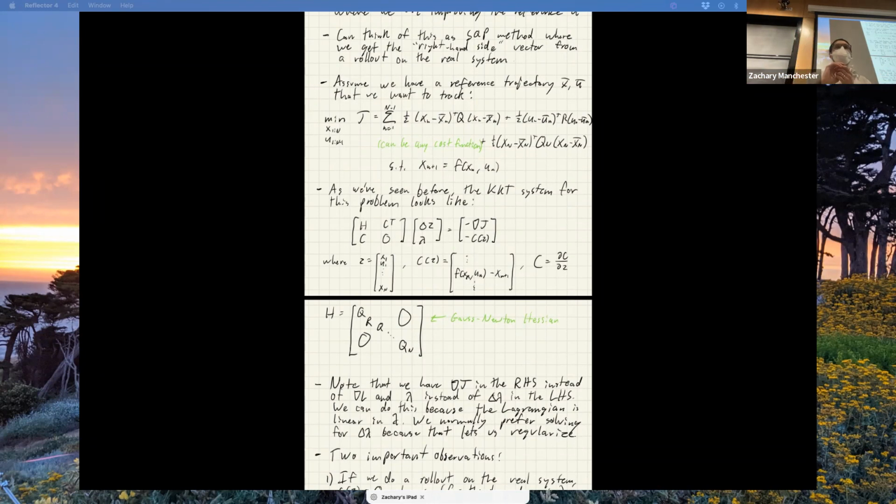If that vector is non-zero, it's telling you that the dynamics are violated when I solve these things normally. Remember we did IPOPT direct collocation and this infeasible start thing where I drew a cartoon trajectory that didn't obey the physics, and then I solved it and it was able to solve. What's going on there? When I draw the cartoon trajectory, that little C of Z is non-zero because I'm violating the dynamics constraints all over the place.